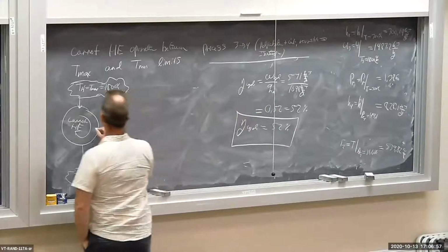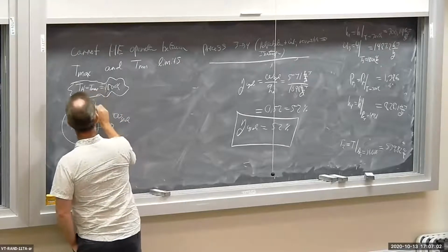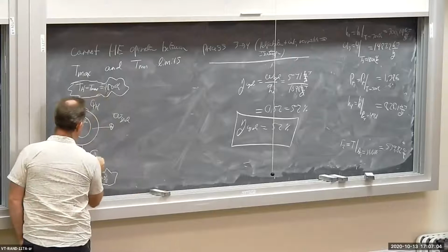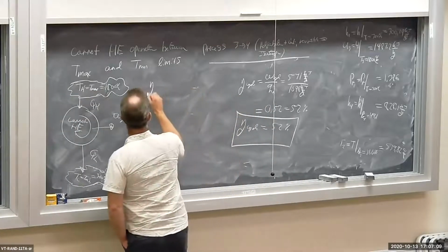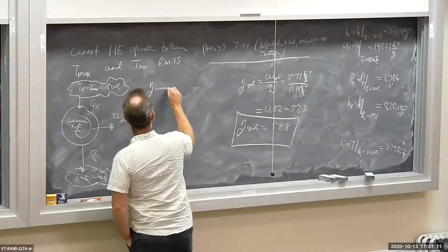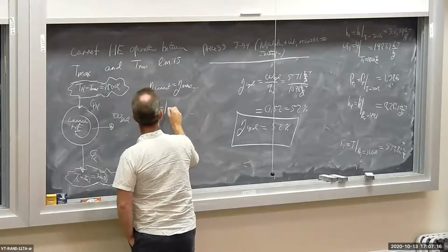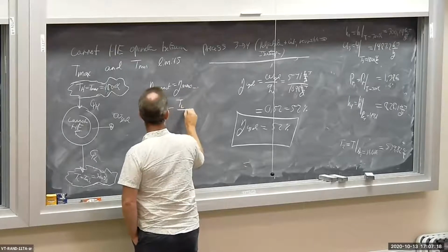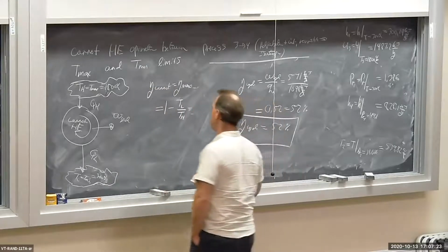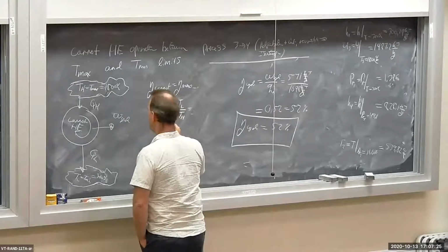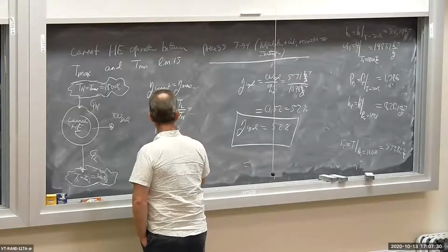So this thing is going to produce a certain amount of work over the cycle. It's going to receive a certain amount of heat Q high and reject a certain amount of heat Q low. The efficiency of the Carnot cycle, which by the way is the maximum efficiency in the cycle, is 1 minus T low over T high. That would be 1 minus 300 over 1800 degrees Kelvin.